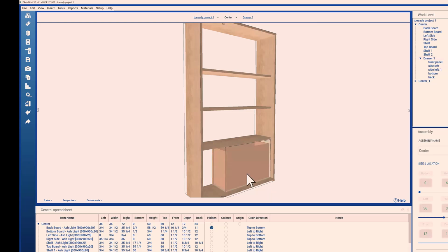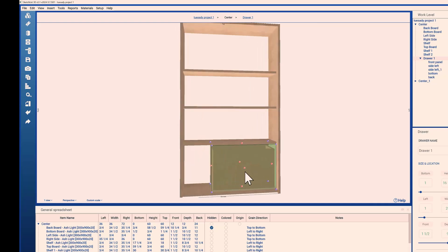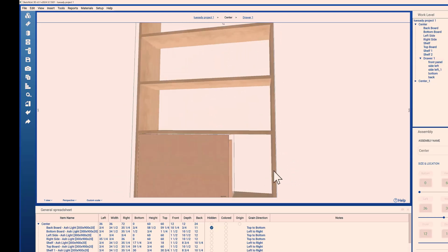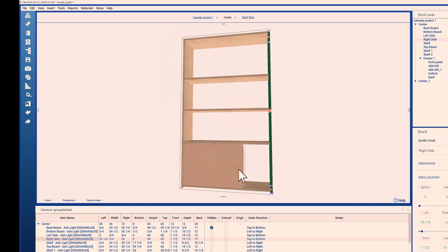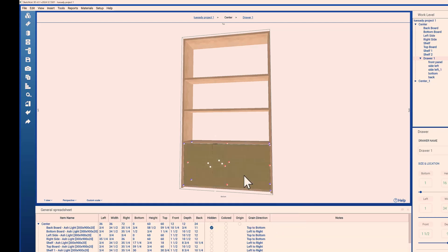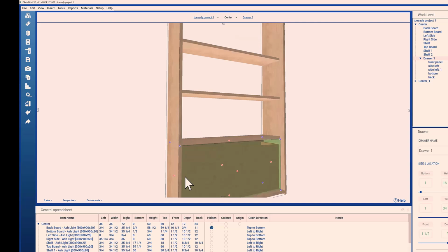Okay. So in this case, say I realize I didn't make our drawer wide enough. What I do is click this, say its left value is 35 1/4. So I can come up here and say the right of this is 35 1/4, moving it over. And it makes that adjustment. I just added whatever it was, 12 inches to all those boards, and it does the right thing.